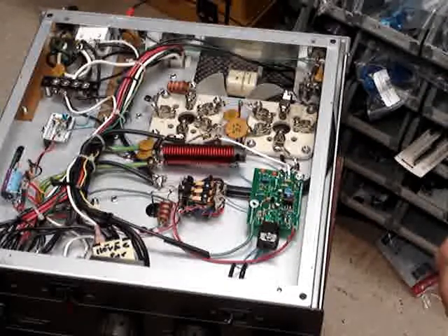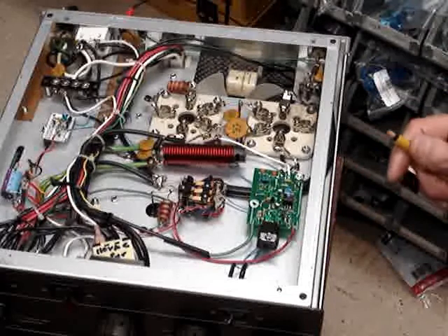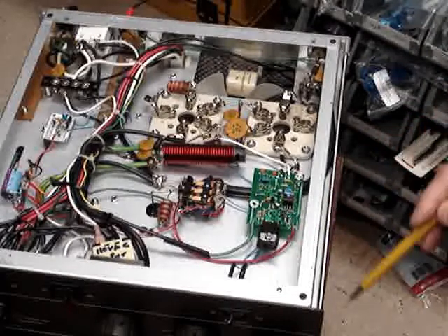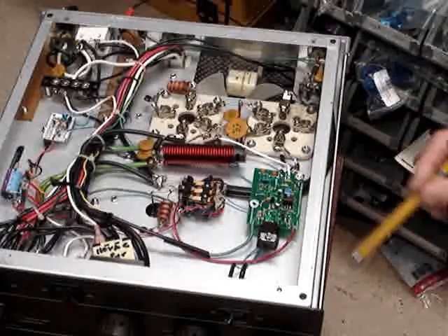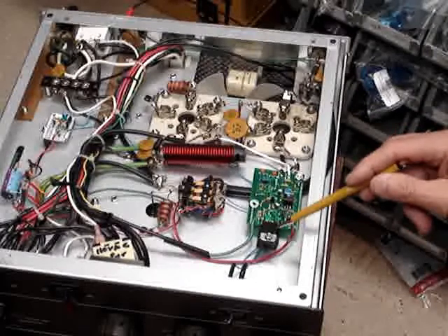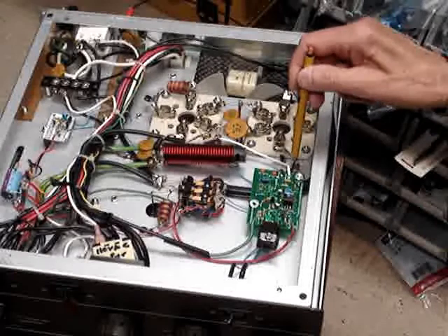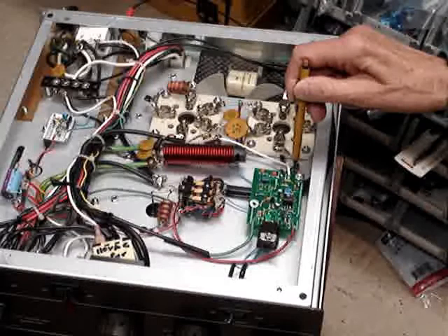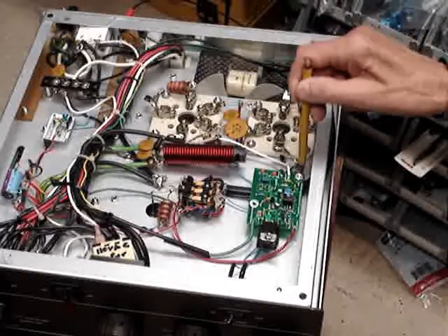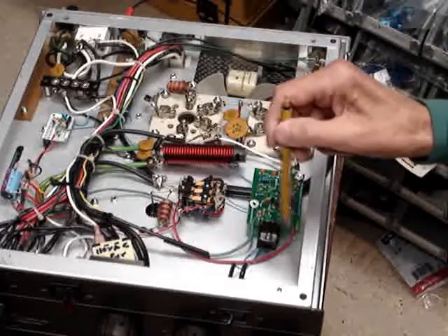Something like an AL811, which only requires about 4.2 volts, would have less dissipation, even though it can draw up to an amp, I believe. And some that use 10-volt bias, now you have to be a little more careful with airflow because you don't want to overheat this. Other than that, the only other thing I've done is I've built a little bracket here to support it. There was an existing screw down here that I loosened, slid the bracket under, and only have one screw holding this. It's more than enough.